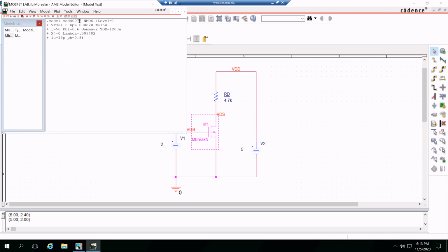So one thing you might be asking before I go any further is, well, what is this model? What does it represent? Anytime a foundry manufactures a component, they're going to characterize it. By characterize it, I mean electrically stimulate the device and pull curves off of it. And these parameters go into a model. That model, you can think of it as just a really big mathematical equation that's a curve fitting equation.